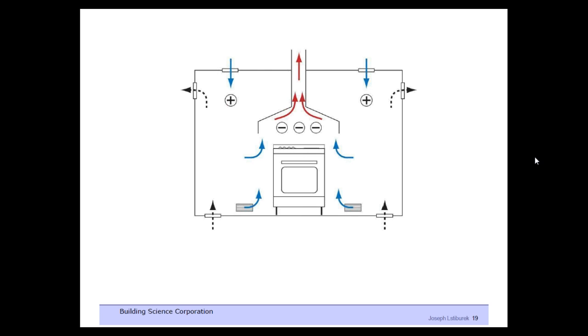You can't have 100% of the makeup air delivered under the unit. You're required to have a zone of negative pressure at the cooking surface, so you tend to provide 70% of the makeup air under the unit, and then the remaining 30% goes into the general space. So when we design these systems with an interlocked fan that's bringing air in from the outside, let's say the exhaust flow at the hood is 100 CFM, we're providing 100 CFM of makeup air, we would deliver 70 CFM underneath the unit and then 30 CFM of that 100 into the general space.